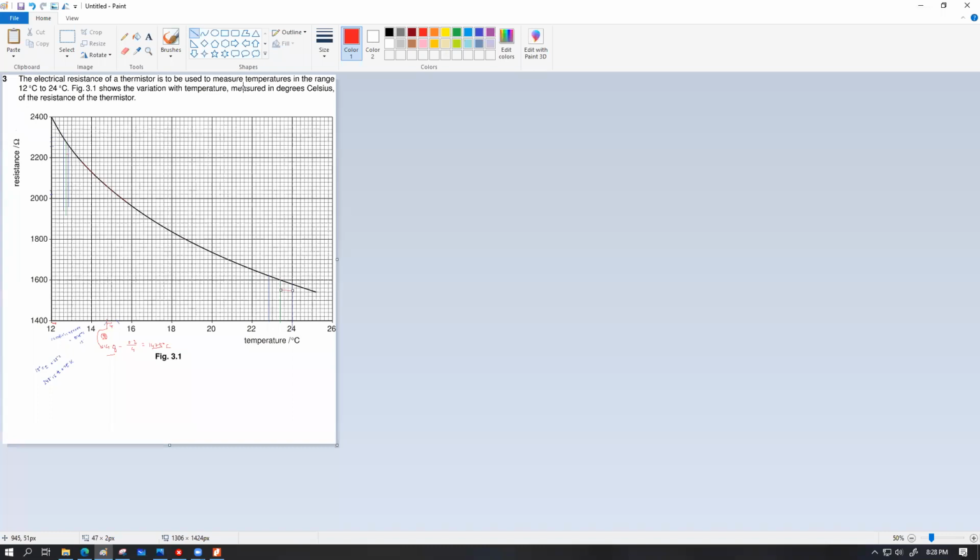Okay, anyway, I got it now. If we want to give a single value of uncertainty for the entire workable range, then we might consider giving an average value. But to be honest, that would not be precise, because that average value would refer to somewhere around the halfway point. As the graph behaves, uncertainty is less for the higher temperature and more at the lower limit. So that might be a workable solution, but it's not going to be a very precise one.